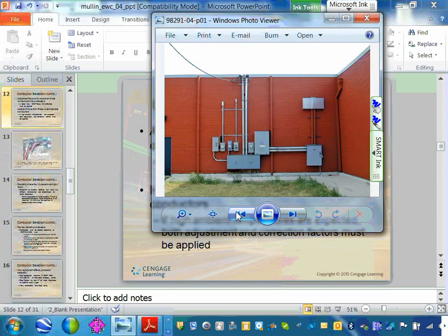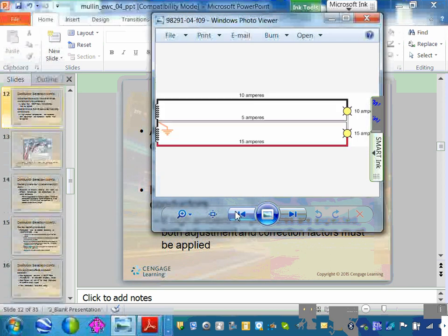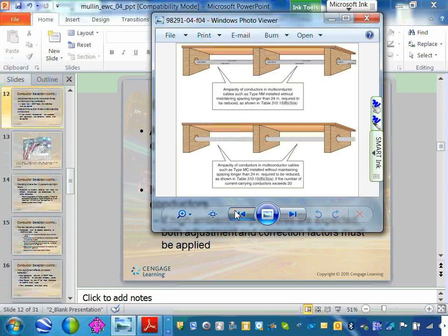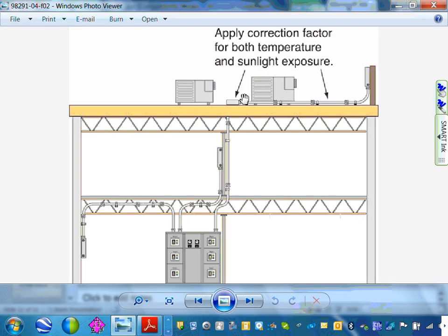But we have a really nice application of a roof. There you go, right here. Do you guys see that one? Do you see these conduits? If you put the conduits in the roof, you put the conductor right through them. So they will be exposed to the sun directly hitting them. That's heat number one. Then reflected heat from the roof.